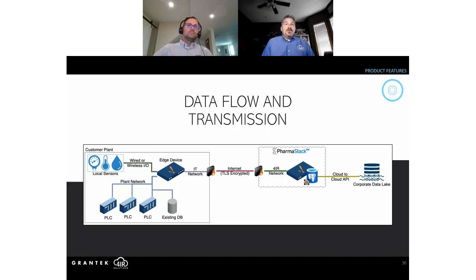The edge device we're using in this architecture is called a Groov EPIC, and it's made by a company called Opto 22. The name EPIC stands for Edge Programmable Industrial Controller, and it allows for a single device to act as a PLC, a communications interface, a data buffer, as well as a failover node.